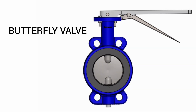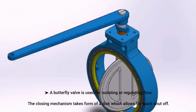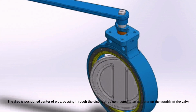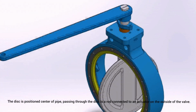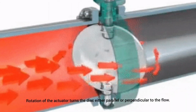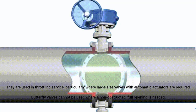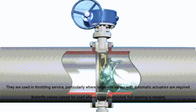Next, butterfly valve. A butterfly valve is used for isolating or regulating flow. The closing mechanism takes the form of a disc, which allows for quick shutoff. The disc is positioned in the center of the pipe. Passing through the disc is a rod connected to an actuator on the outside of the valve. Rotation of the actuator turns the disc either parallel or perpendicular to the flow. They are used in throttling service, particularly where large-size valves with automatic actuators are required. Butterfly valves cannot be used where a non-obstructed full opening is needed.